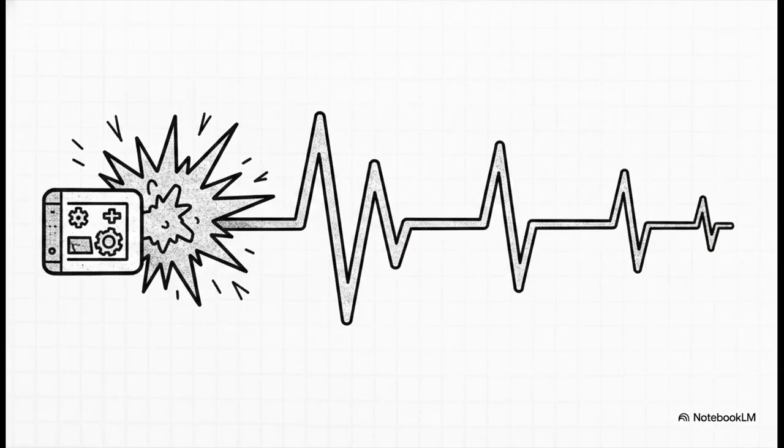You see, the instant a fault hits a generator, the fault current doesn't behave like a simple resistor circuit at all. No way. It's a highly dynamic, really violent event. When that short circuit occurs, the current slams to this massive peak. But it doesn't just hang out there. It actually decays in 3 distinct, predictable stages over the next several seconds.